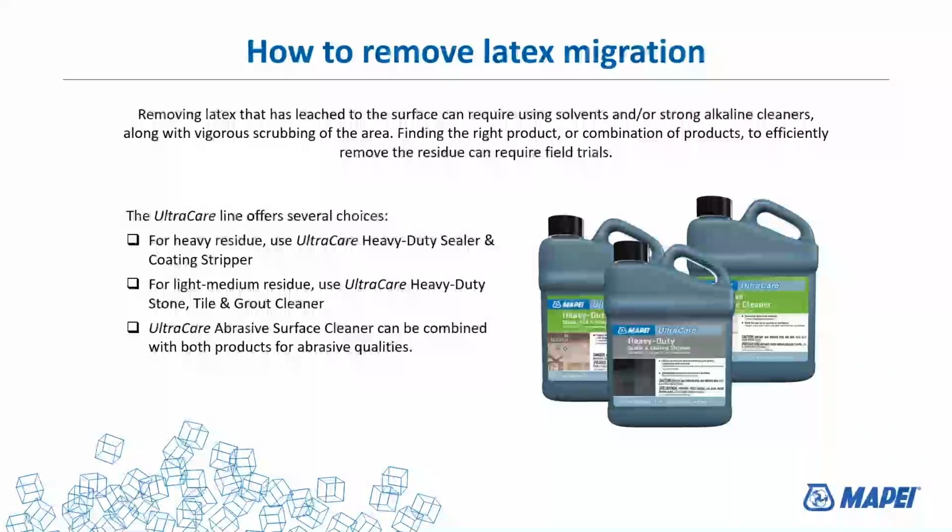So if you've got heavy latex migration, I would tell you to hit it with the stripper first and let it sit there. The dwell time could be 20 minutes, 30 minutes, an hour. It would depend on how much is on the stone or grout and how much needs to be removed, and how old it is will dictate how long the heavy duty needs to sit.